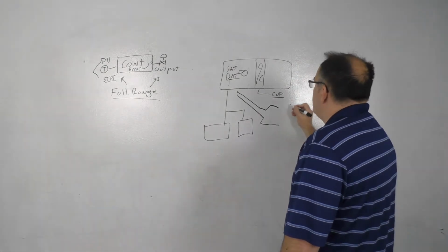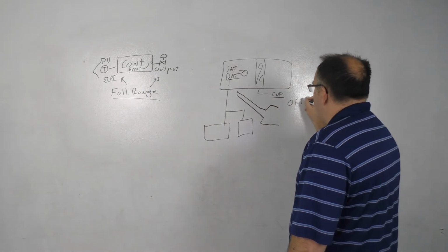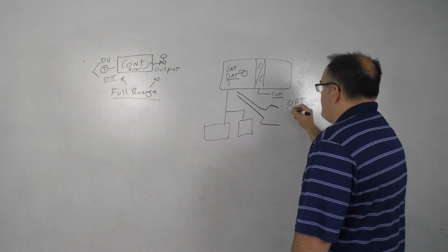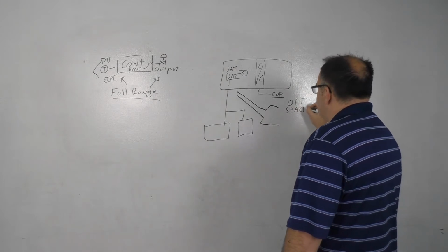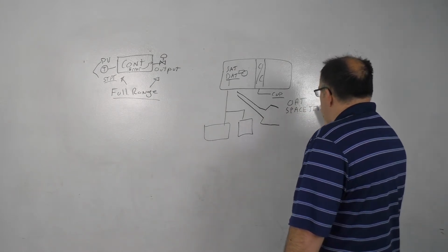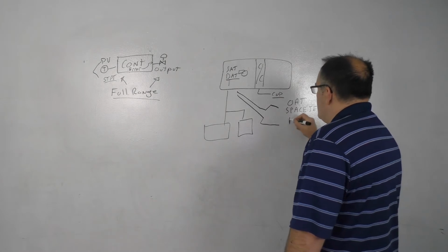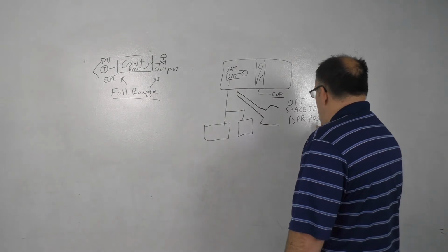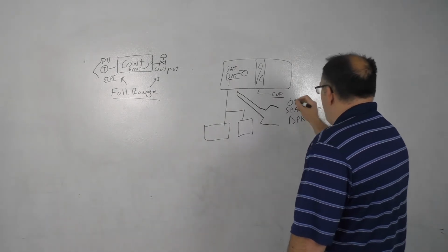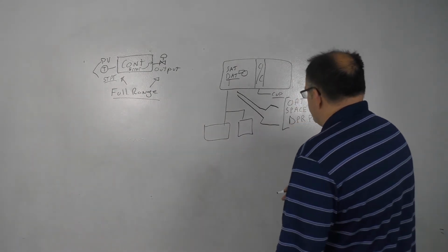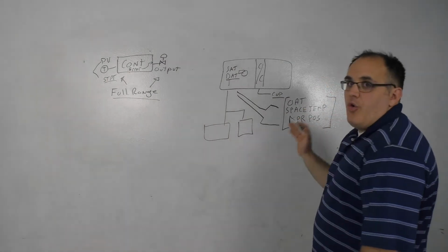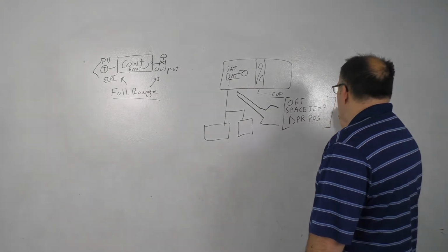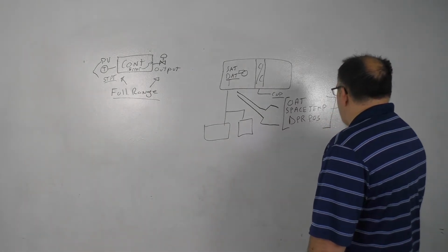So what we typically have is a couple different variables that we can reset off of. We can do outdoor air temp, we can do space temp, and then we can do damper position. Okay? These three variables are kind of in the order of what I would recommend. And when we say space temp, we could also throw in there RAT, return air temp.